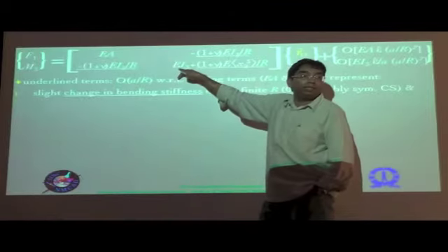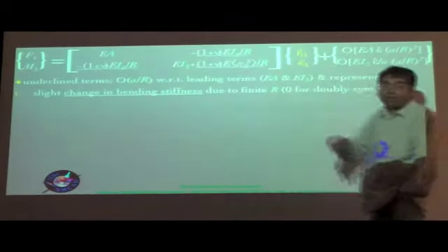It would remain EI3 if it were a doubly symmetric cross section. Of course, for this problem, we have already assumed for planar deformation that the cross section is symmetric about this plane. So, in other words, if you look at it either in front of the screen or behind the screen, it would look like a similar cross section.